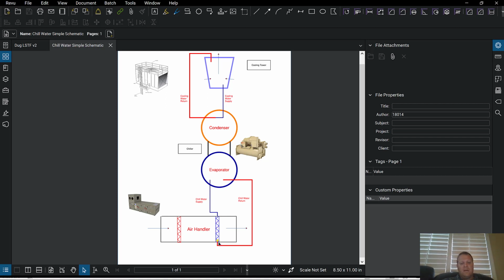And then just by way of cooling off the air, the heat had to go somewhere. So the heat went into the chill water. It went into the coil and into this chill water return line, and it goes back to the evaporator to follow the cycle again. Now we need heat exchange here as well.